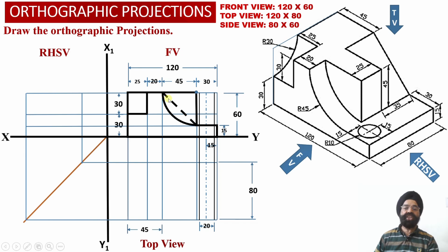This is the projection of the inclined surface which is not visible to the observer from the front view orientation, because this inclined surface happens to be overshadowed or covered by this vertical web, right? So this way we have been able to obtain edge view projections corresponding to this inclined rectangular surface, as hidden line projections into the front view projections over here.